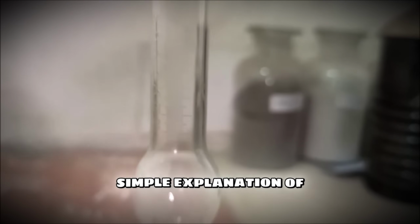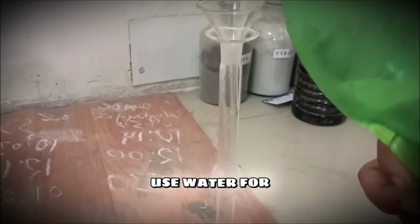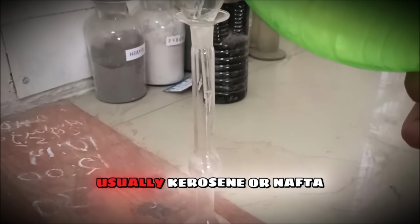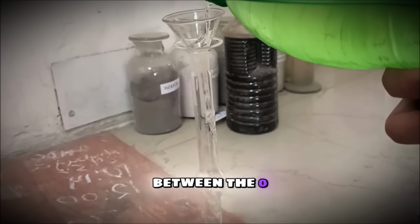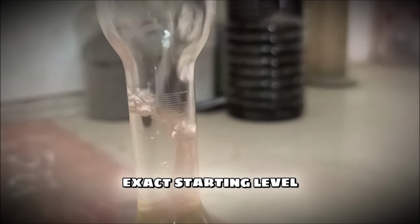Here is the simple explanation of how you use the Le Chatelier flask. Because we can't use water for reactive materials, we use a non-reactive liquid, usually kerosene or naphtha. Step 1. You fill the flask with kerosene to a point on the neck between the 0 and the 1 milliliter mark. You read that exact starting level.